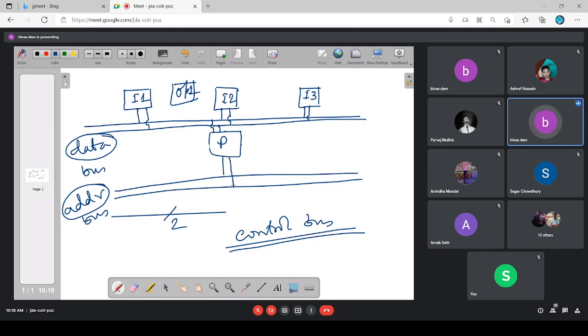Normally, all the IO devices are equipped with an internal decoding system. So in that case, there is no need for an explicit decoder inside the system, because I can simply transfer the address information to each of the input devices and output devices as well.